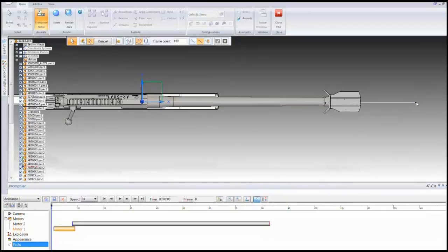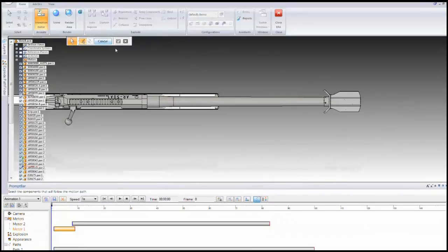So we'll just pick a point right out here, and if you want to define a more complicated path, you can pick more than one point. If you want a curved path, you can do that. You just place the next point and it'll curve it, or if you want a straight path, you can select that option up here, and then your path will be straight. We only have 2 points because it's a real simple path. So we'll pick that, hit Accept, and then we'll finish it.